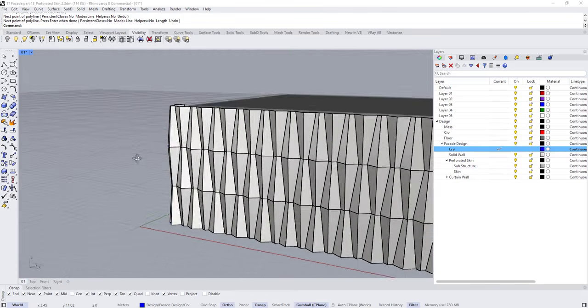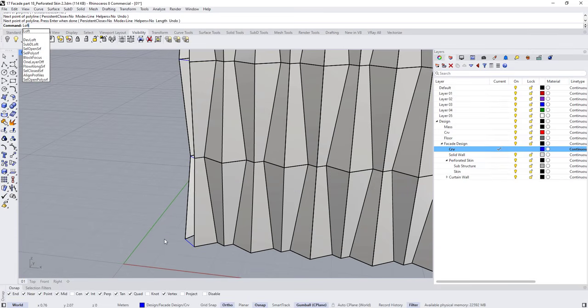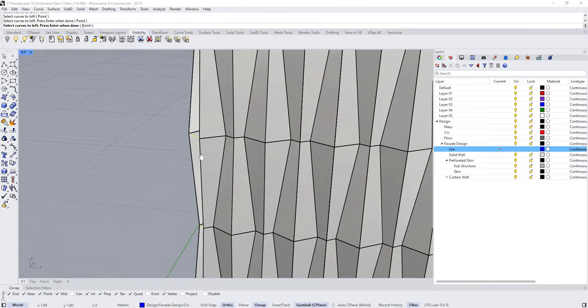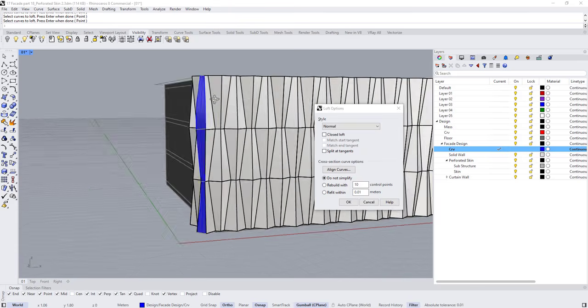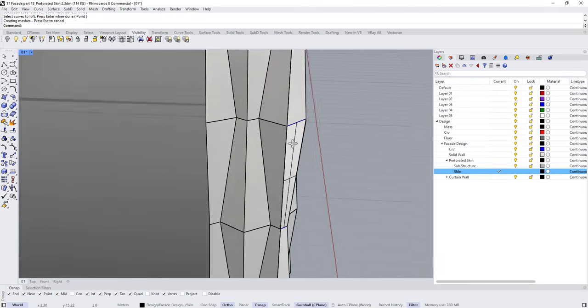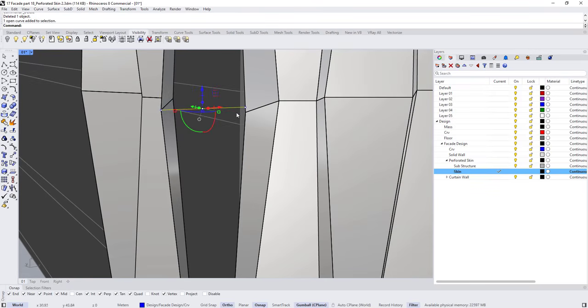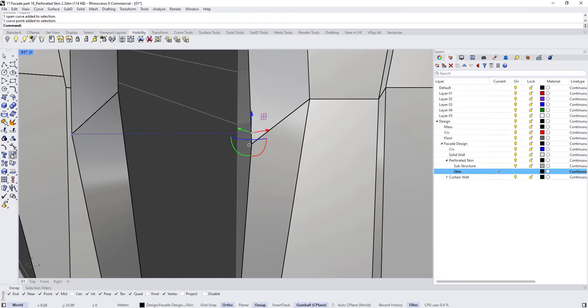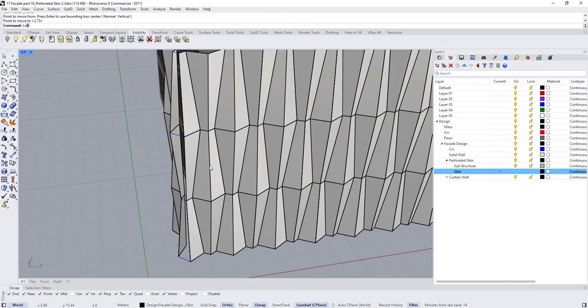So we can keep it something straight and create maybe a loft between these parts. But let's make it straight sections. The skin layer. You have something. Okay, yeah, delete this one. Make sure the lines are placed in these vertices. Type loft. Here, here, here, and here.